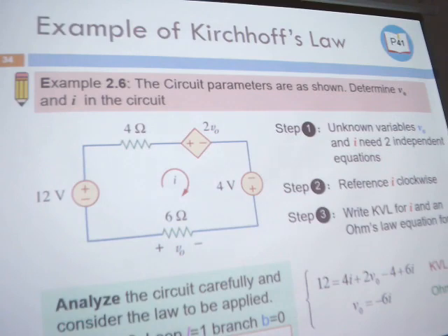So the equation is right actually. Understand? Because if the step like the 6I is directly, our first equation is minus V0. So V0 equals minus 6I, so the result should be the same. Just because here I didn't follow the direction of minus V0. I just write down a KVL law, use my direction. Then I find out a relation for V0 and 6I for this resistance, and I got this one.